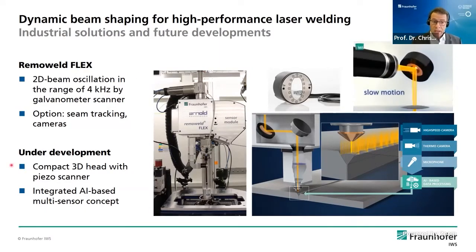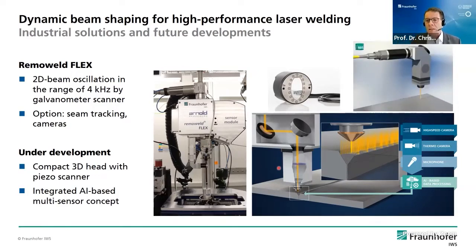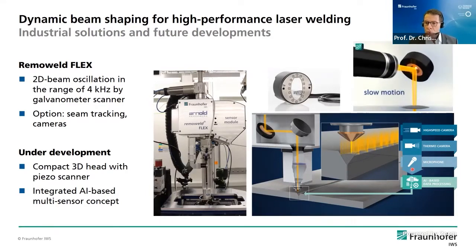So the next step, the future, will be to develop, and this is just under development as we speak, a 3D head using also the z-axis direction for controlling the energy input into the melt pool. And this will be complemented by extensive sensing using high-speed cameras, a thermal camera, as well as a microphone using acoustic emission to sense the welding process.